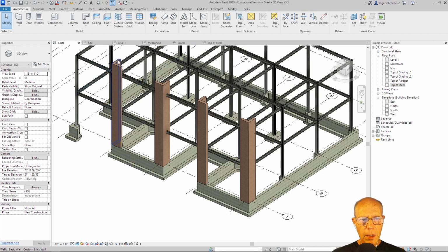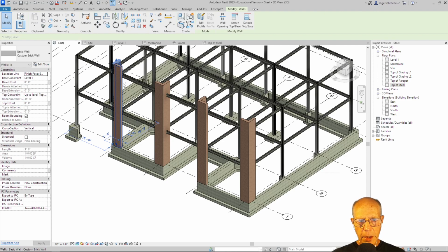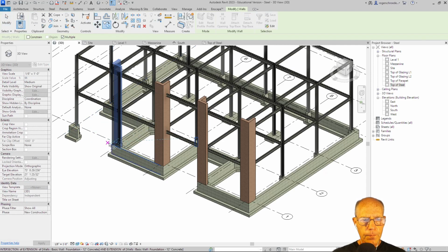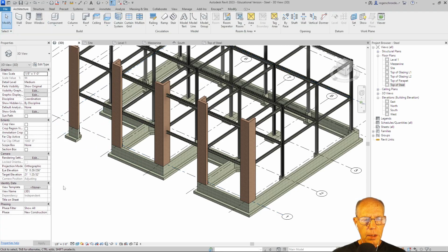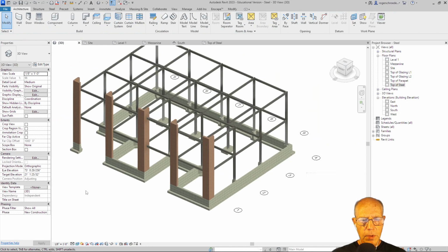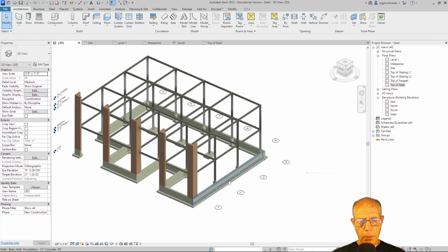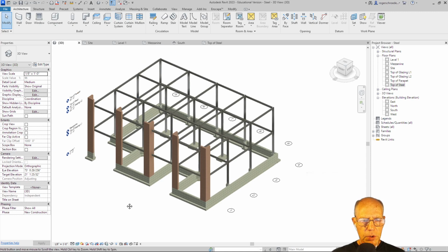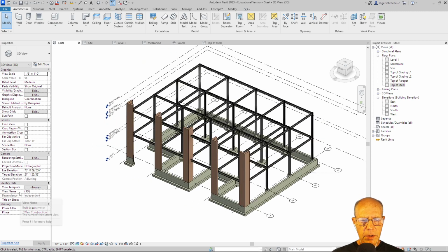And let's do this one last time. I'm going to grab this wall again, and grab the copy tool, and come to that top corner, and move it over here, and place it again on that other corner. So that's enough of our starting. We're going to add a couple of more pieces of wall in here and some other clips, but I think this is enough for our first CV2 assignment. So next we'll look at creating a presentation sheet for this.